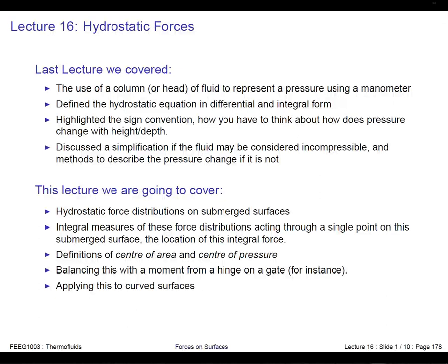where this volume has the particular curved surface that we're interested in as part of its boundary. We do a force balance on this volume and use that to work out what the forces must be on our curved surface. This is much easier than defining a coordinate system that tracks this curved surface.